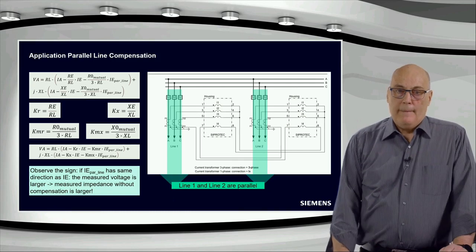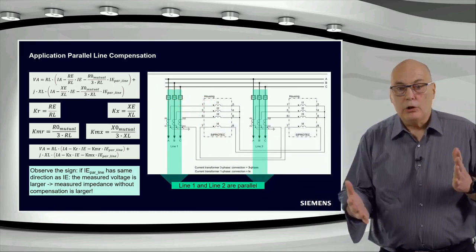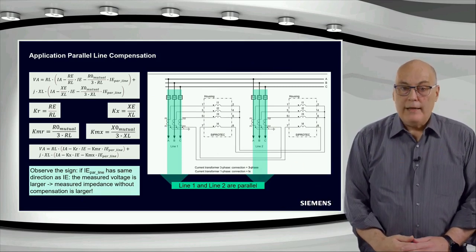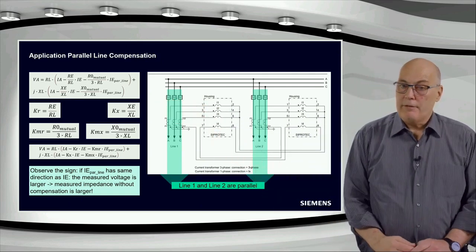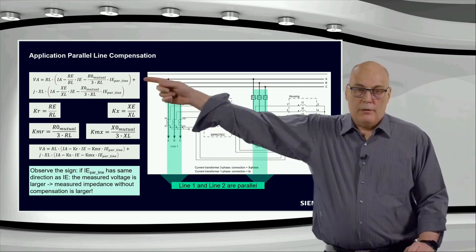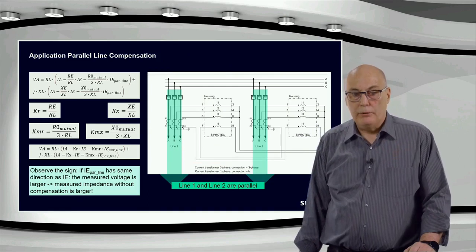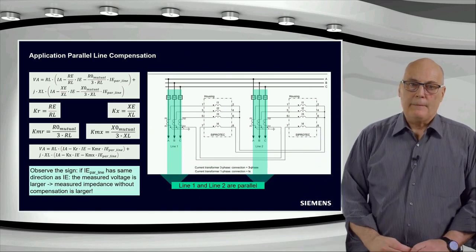At the top, you can see that previous voltage loop equation, now extended into the KR, KX method. So it gets a bit longer, but it's essentially the same thing. You can split the real and imaginary components as shown in the two top equations. That's the same voltage loop equation, but not written with Z's, but with R and jX.